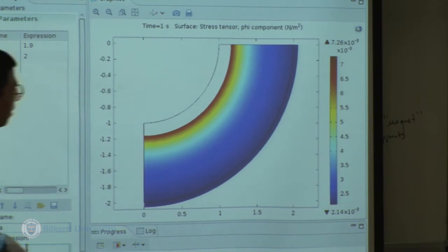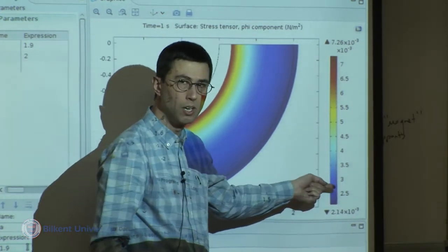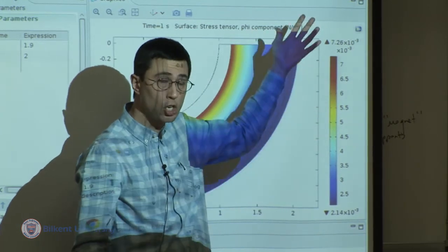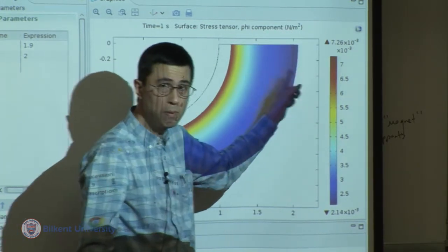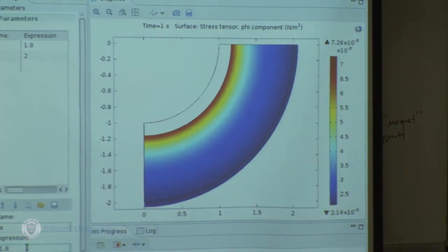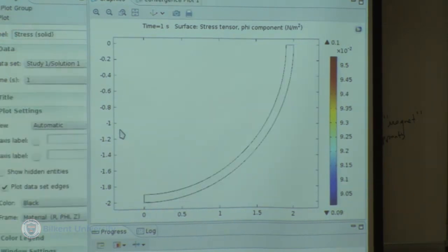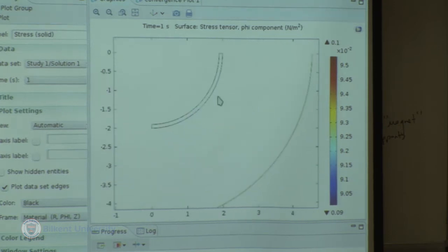But what we're going to essentially see is that the stresses, which were changing by a factor of almost 3, are going to become much higher, and the variation is going to be much less. That's what we're looking for, because that is the nature of a thin-walled solution. So I go ahead and compute the new solution. Of course, because it's becoming thinner, the compliance of the thing as a whole is increasing. So it blows up like a balloon because the pressure is the same pressure.